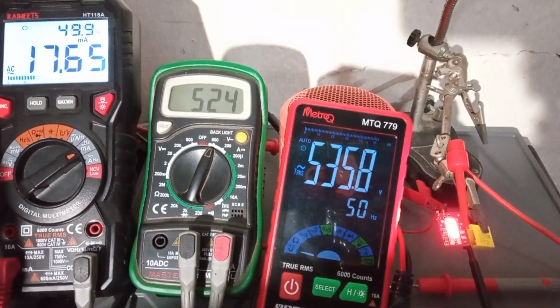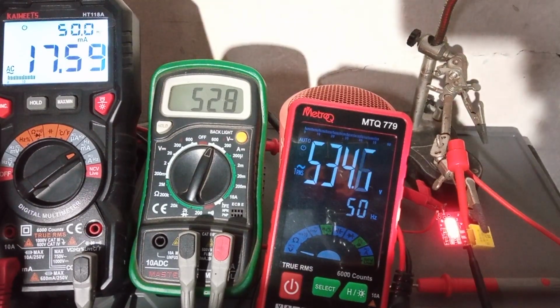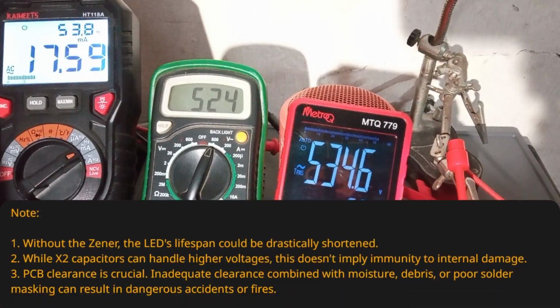And the thing to note is that capacitive droppers, even if they are rated for lower voltage, can actually take higher voltage if they are good capacitors. Now there's a problem. If you go above a certain limit, the capacitor might blow up, and because I have a fusible resistor, that might protect it a little bit, but it is currently not limiting the current that much, and the capacitor is dropping most of the voltage.